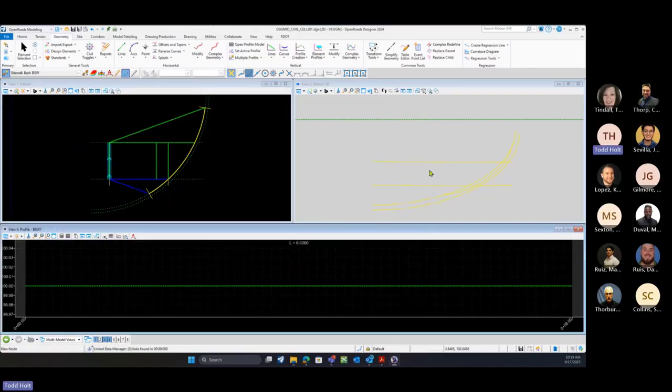And we're going to start building our outline of our sidewalk that we're going to build that terrain model for and build off the surface I put on. So on this line, we're going to do a project profile intersection point.